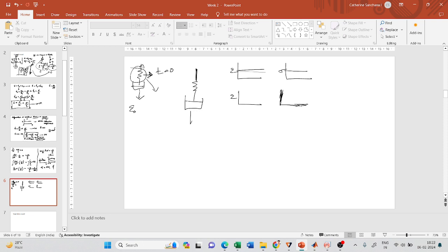It needs to have an infinite stress at time t equals zero, right? So, when I apply a strain to the material, the first thing to deform will be my spring. The dashpot will take some time to deform.